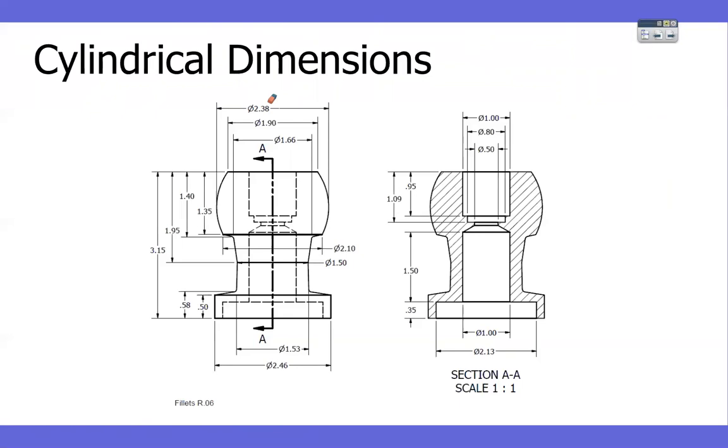So the standard is that the outside of cylinders is dimensioned where you can see it from the side, not where it's round. Holes are usually dimensioned where they're round, but if there's something complicated going on like this, we can look at it and dimension them here also. They will have the diameter symbol. So by seeing that symbol, you know that it's round, right?